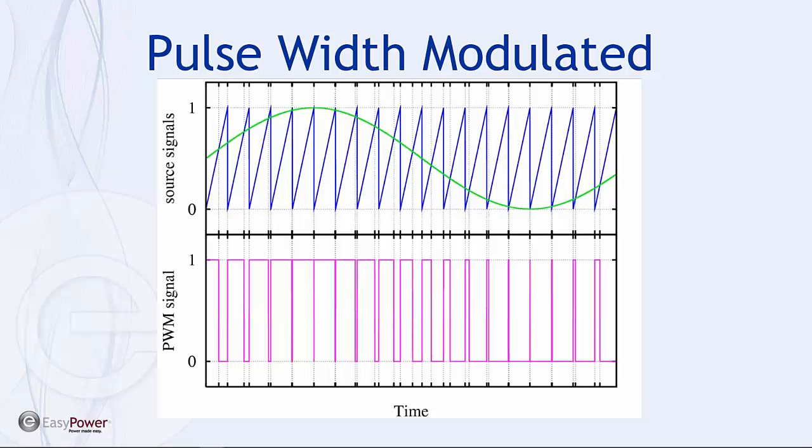So you can see on the bottom layer that we have wider positive-going pulses, and on the negative side of the sine wave, we see more width on the bottom of the pulse width modulation chain. Now, this frequency, the sine wave, is the frequency that's actually going to drive the motor. The switching frequency, that of the sawtooth, is what the switching elements are going to be running at, and these all have a part to play in terms of the impact on our system.